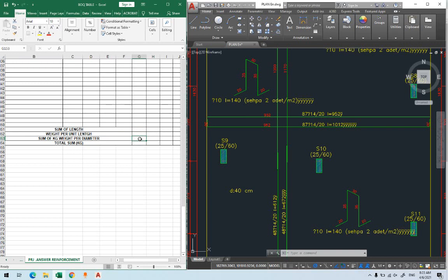This is how we calculate it in kilogram. You find the total length, then you have a weight per unit length, you multiply them, and you get, for example, I calculated and found 1590 meters I need of this, and let's say the weight is 0.6 kilogram per meter. You simply say this times this one.